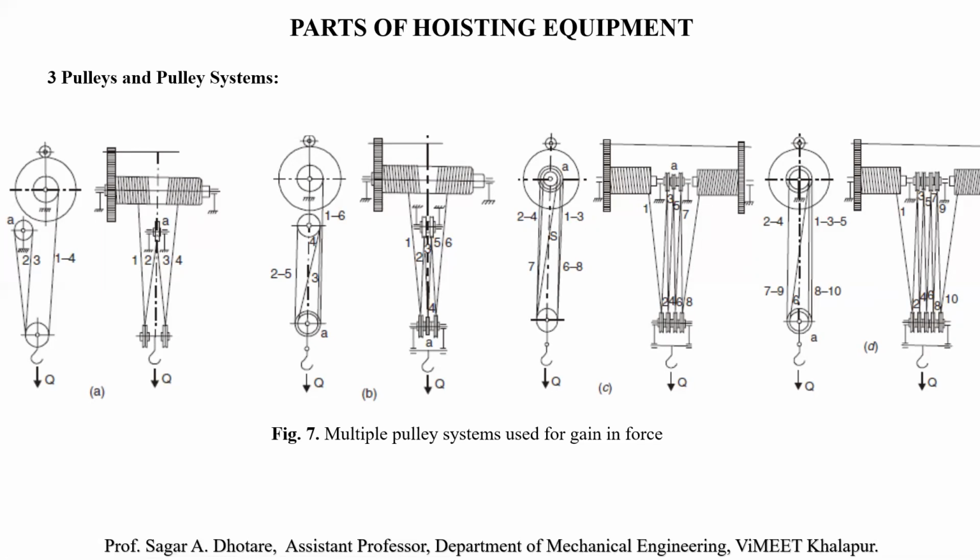In this system, two ends of the wire rope are fixed on the drum, or two drums, with right and left hand helical grooves. The rope passes from one half of the pulley system to the other by means of a compensating pulley, which simultaneously equalizes the length of the rope parts when they are stretched uniformly.